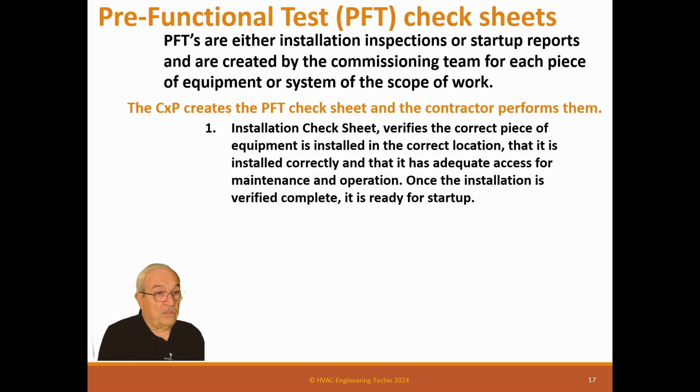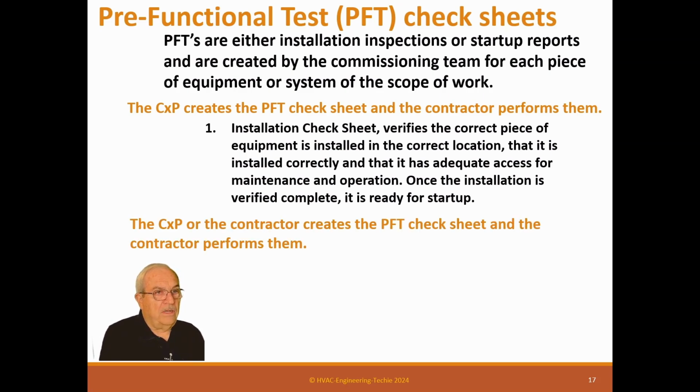It's superficial at best. A lot of guys have just taken the equipment manufacturer's first pre-start list, which does not include operability, maintainability, all that stuff. It just has to do with how you get it in the air or on the ground and get it ready to start up. But you need to make sure they're robust enough for that. The CxP or the contractor creates the PFT check sheet and the contractor performs them.